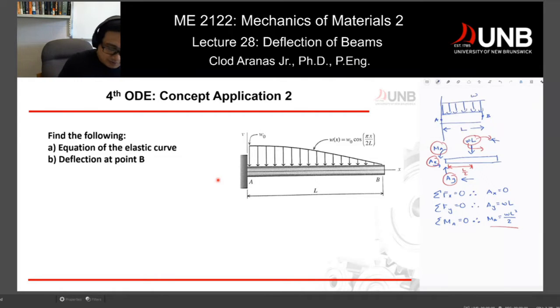Now, what do we mean by indeterminate beams? Let's say we add another support reaction at the end of this cantilever beam. Say we add a roller support at this point, this one right here. Once we add a roller support, we have another unknown. That unknown is a force, B, or we can call it B sub Y, acting along Y, which makes the system indeterminate.